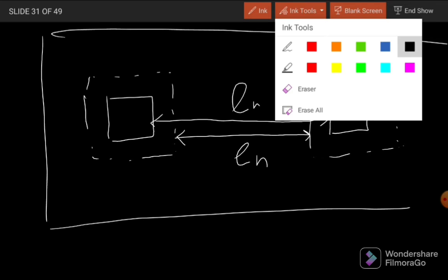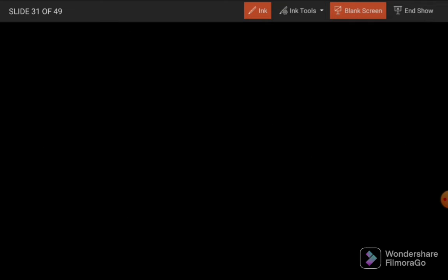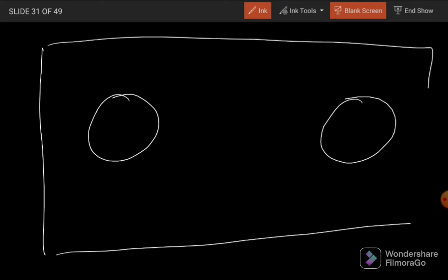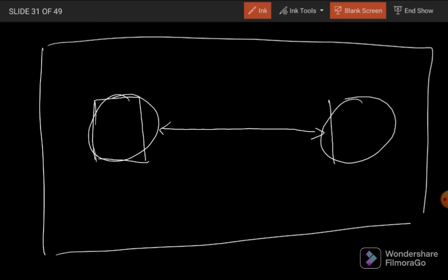Okay. So if the column is not a rectangular column, for example, here we have a circular column, so I draw this again. Here we have a circular column and a circular column. So in this case, the clear span will not be like this, from the surface of the column to the surface of the column. Instead, first we need to convert this circle into an equivalent square, like this.